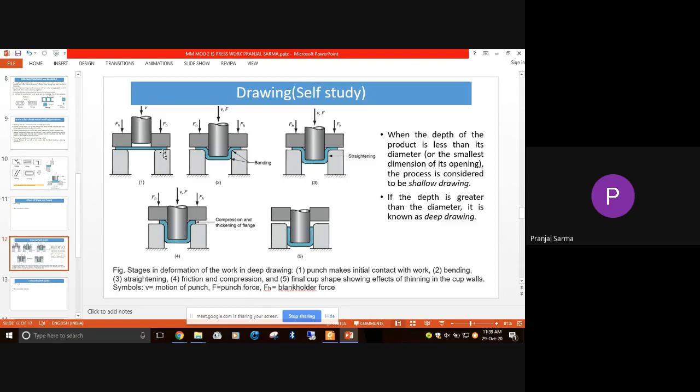So how do we perform deep drawing? Once again we will have the die and the punch. The die is generally the lower one and it is generally fixed, and with the punch we provide the required force. In this figure, the blue part is the sheet metal, and it has to be clamped properly. This shows the clamping force that we are seeing.